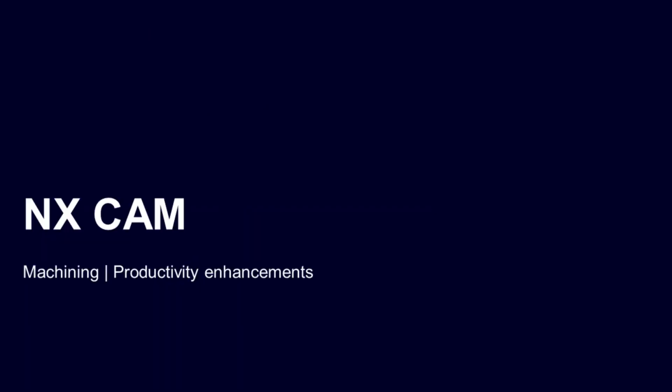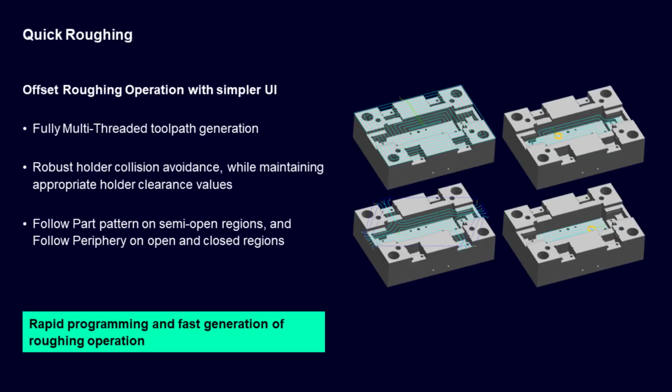First, let's look at the enhancements in NX CAM, one of the most comprehensive solutions for NC programming on the market today. A new roughing operation, called Quick Roughing, is now available. The operation is recommended for programming and machining of simpler prismatic parts, mold cavity and cores, dies, casting, and forging with contoured shapes using planar cut levels.